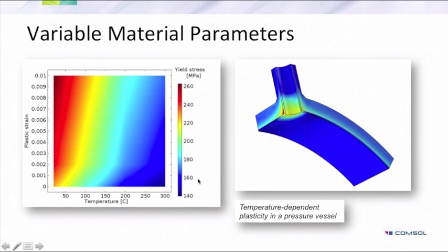This material is used in the example where a pressure vessel is subjected to an internal pressure, and where a hot environment suddenly becomes cold. In case of emergency, there will be cold water coming into the smaller pipe, into the bigger pipe, and there will be some thermal stresses around. The structure consists of two materials. There is one which is going around, it's very thick, and then you have a cladding on the inside, which has better properties against the corrosive environment.